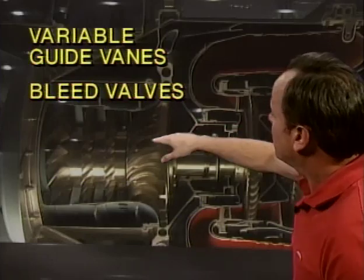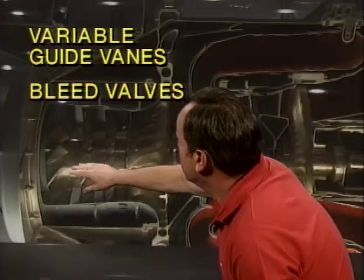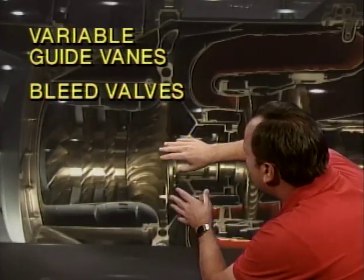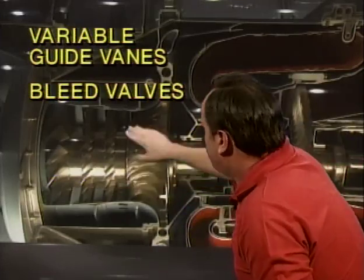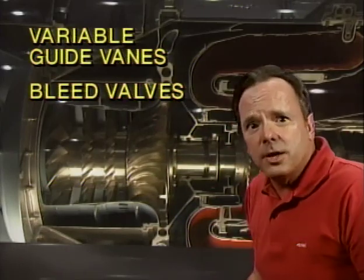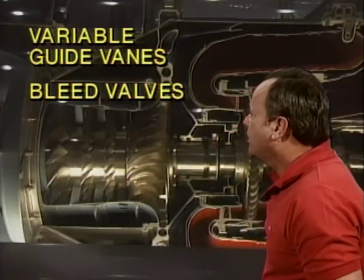One of the things you can do is have variable guide vanes. Now, variable guide vanes adjust the flow of the air going into the compressor to keep it smooth. The other thing you can do is have bleed valves, and bleed valves bleed off some of that compressed air so that you don't make the compressor blades work as hard. And both of these, the variable guide vanes and bleed valves, are used in turbine engines to aid in stabilization of compressor airflow. And what that does is keep that air going smoothly through the engine, particularly important during low-thrust engine operation.